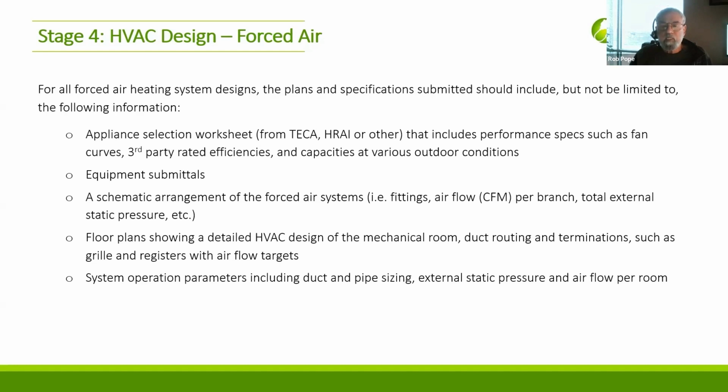And also your airflow targets. You've got a register in the living room on the west wall. How many CFM are you expecting to get out of that grill, so that you can check it at the end to make sure you got it? At the beginning, you know what you need, write it down, and at the end, check to see that you got it.